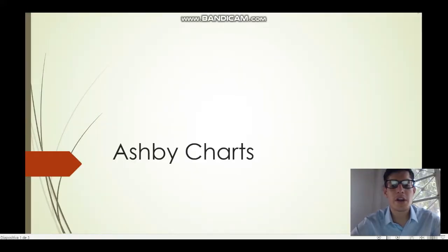Hello, we are going to talk about the Ashby charts. First of all, what is an Ashby chart? It is a chart used in the material selection process in order to select the best material for the specifications that we are going to want to use, or the most effective way the material can be used.